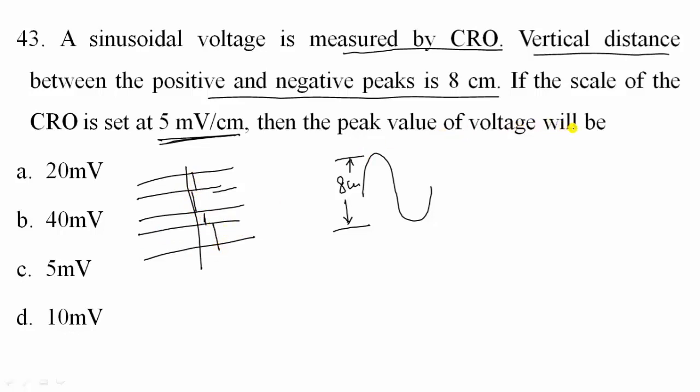Then the peak value of the voltage will be, so they are not asking for peak to peak, they are asking for the peak value, meaning what is this value. So what is this value means, you will be getting 8 boxes over here, nothing but 8 centimeter.